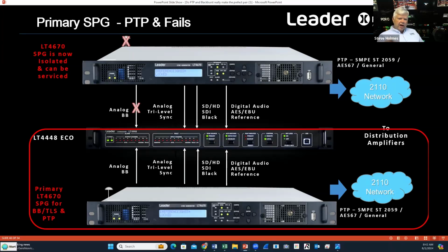The two units are talking to each other, and one unit sees the announce messages and sees that, hey, you're no longer clock class 6, you're clock class 248 because you lost the GPS. It says, hey, I'm still clock class 6. I'm better than you. You be quiet. I'm taking over. And the second unit just takes over. It's a very soft switch versus yanking the fiber, which is a complete LOS, lost the signal.